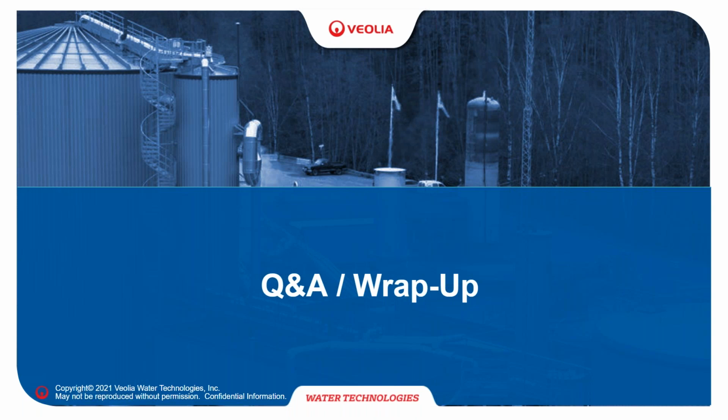I have to say in a high rate system, the volume to some extent does matter because in a number of cases, you need a minimum depth of sludge to get good performance, but that varies from plant to plant. So some plants may need 10 feet of sludge in a UASB, others may need only 6 feet. And that's really wastewater dependent.